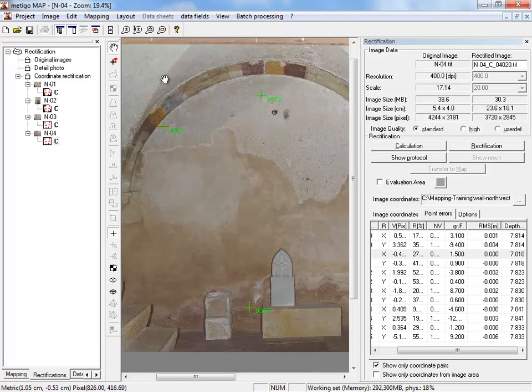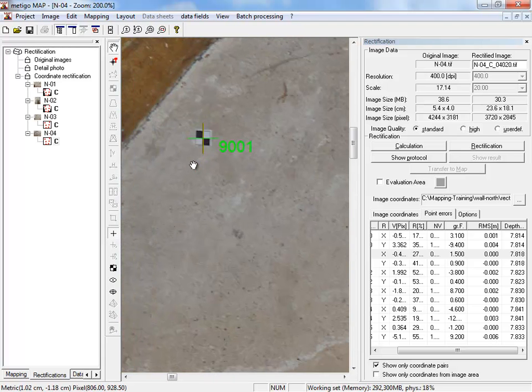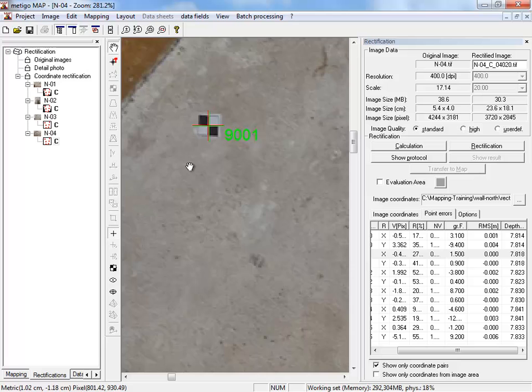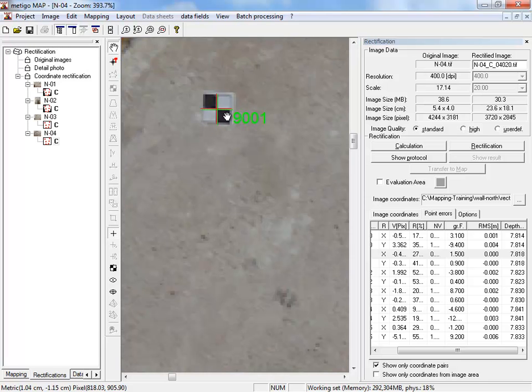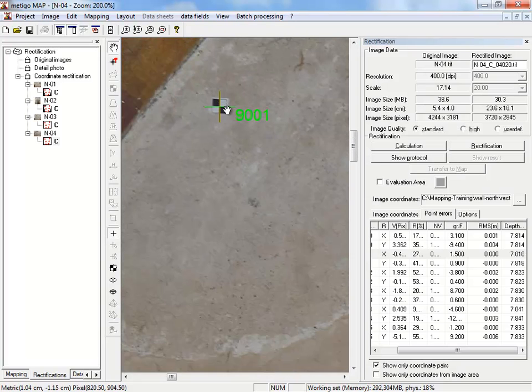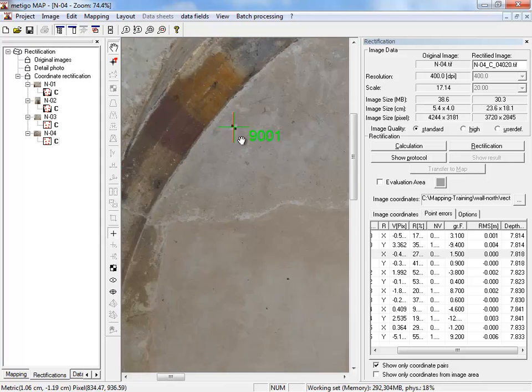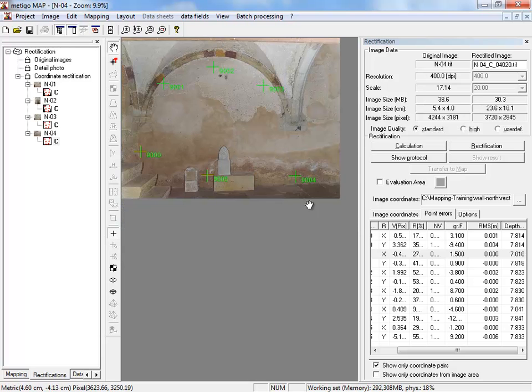The accuracy of control points is far better than of natural points. You can measure them correctly with the total station and have a higher accuracy with the automatic measurement of these control points. And therefore the result is far more precise than the rectification with the CAD file.